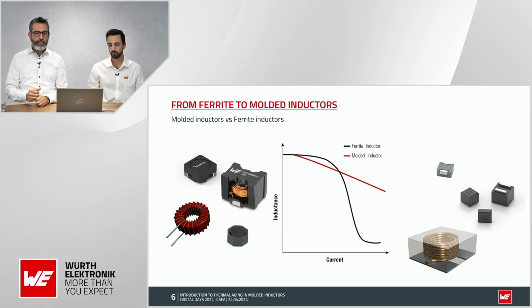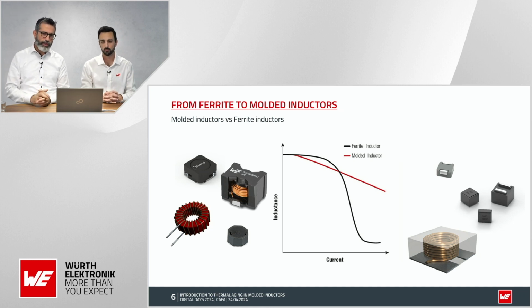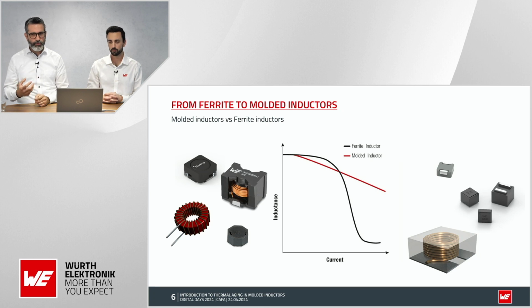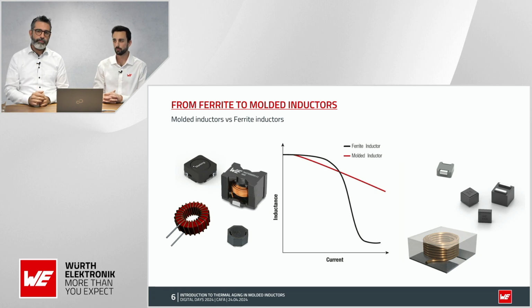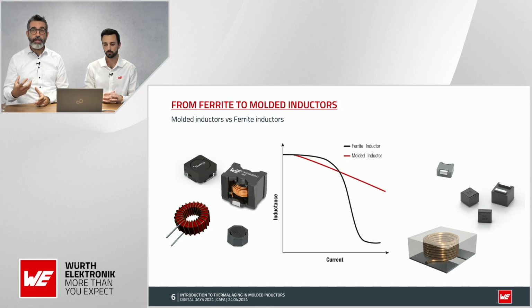By the way, molded inductors have better saturation behavior. The saturation drops gradually over time. They even start to saturate earlier, but it is soft.